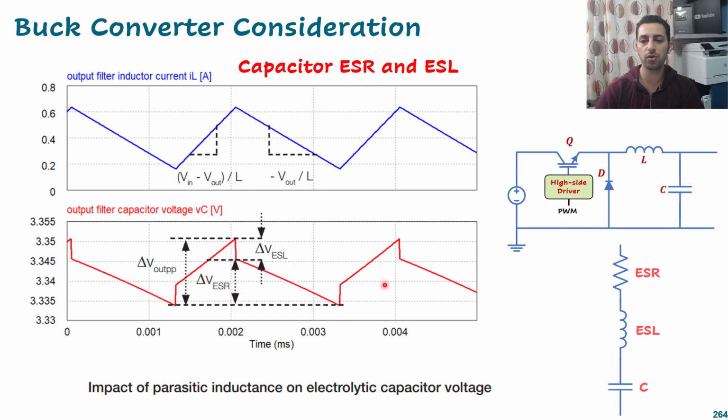Okay, so we are looking here for a very minimum sinusoidal waveform because it smooths that waveform, and we should see something like this. Okay, but this is not appearing here. Why? Because we have ESL and ESR. Now, why is there some steps here if we have ESL?